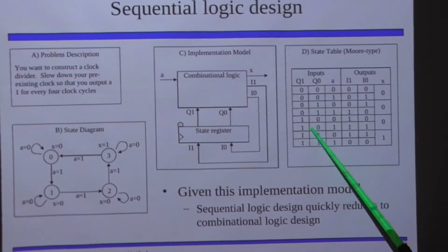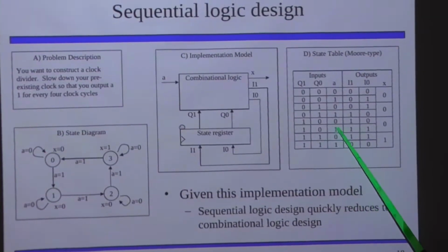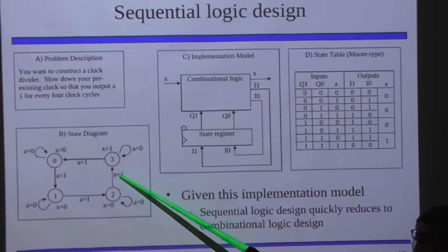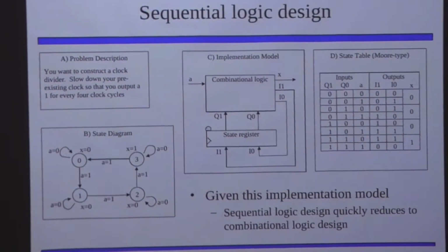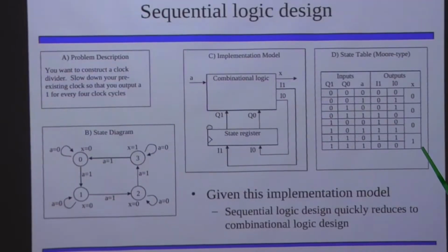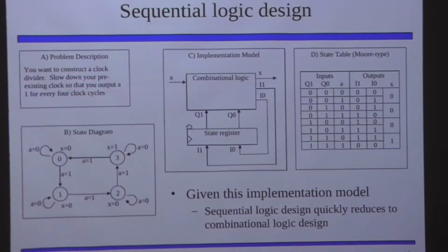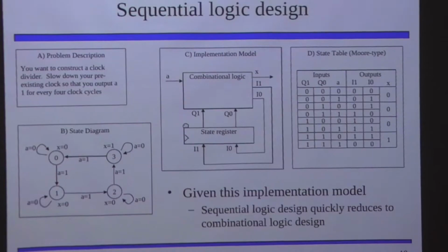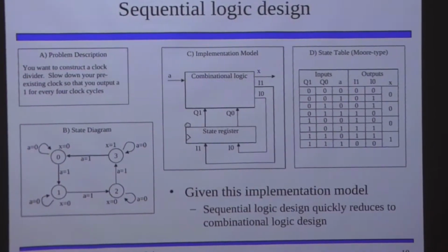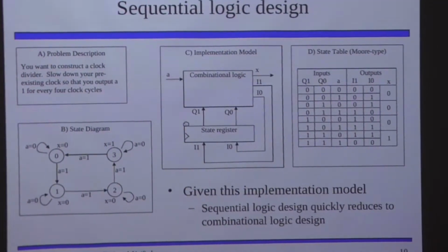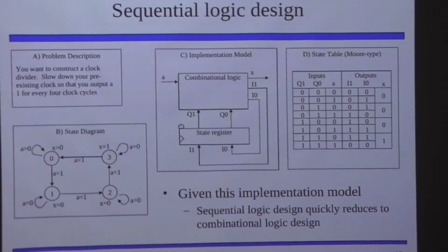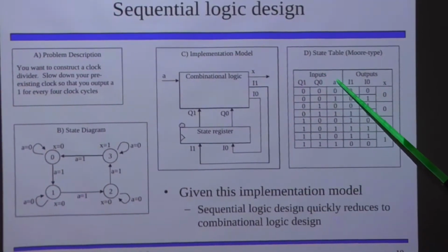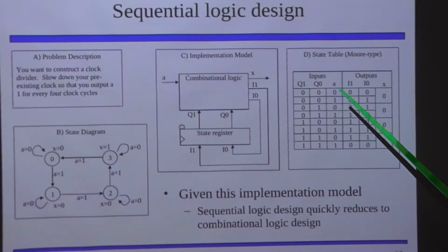That being said, obviously there are some drawbacks to this design. If you're encoding only 2 bits, obviously, you can't go any further than that, right? But this will be fine for the purpose that it is, right? Again, we're not designing a general purpose component. We are designing a single purpose component, and that single purpose is to downscale a clock signal by a factor of 4, specifically.